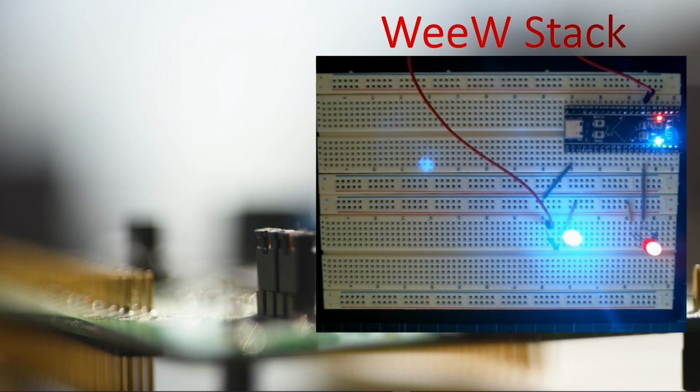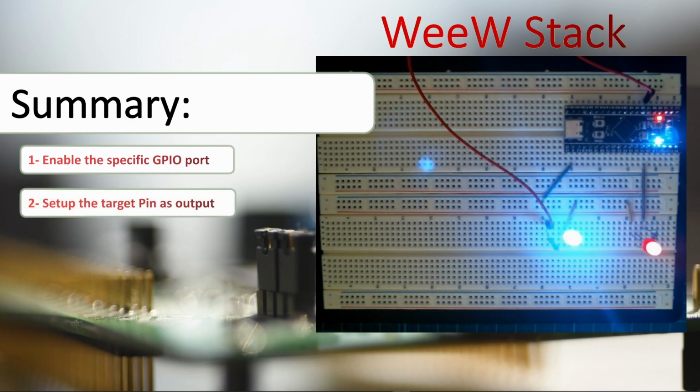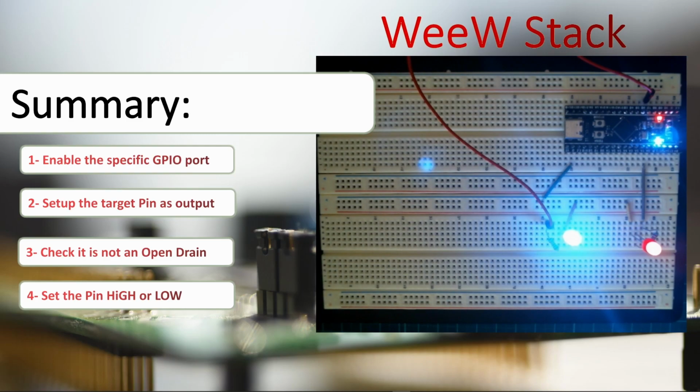So now it's a good time to have a summary. First of all, we started by enabling the specific GPIO port using the RCC register. Then we set up our target pin within the GPIO itself as an output. After that, we checked that that specific pin is not in open drain state. Finally, we set up our pin high or low depending on the requirement that we needed.